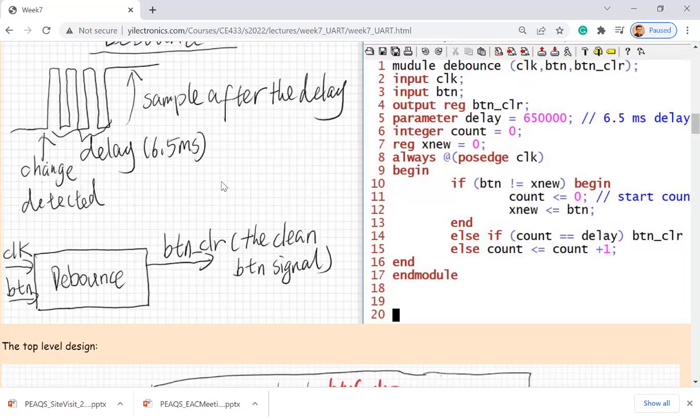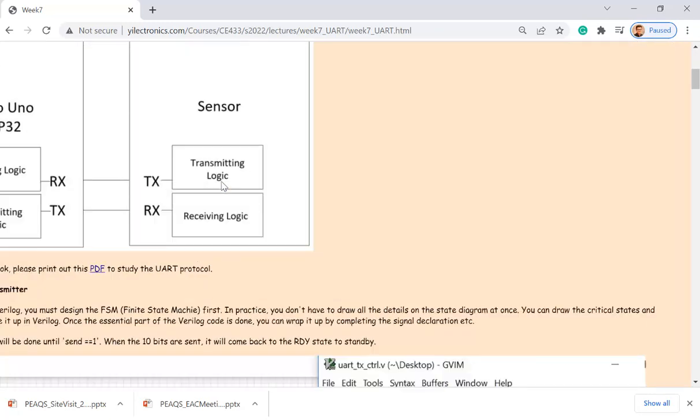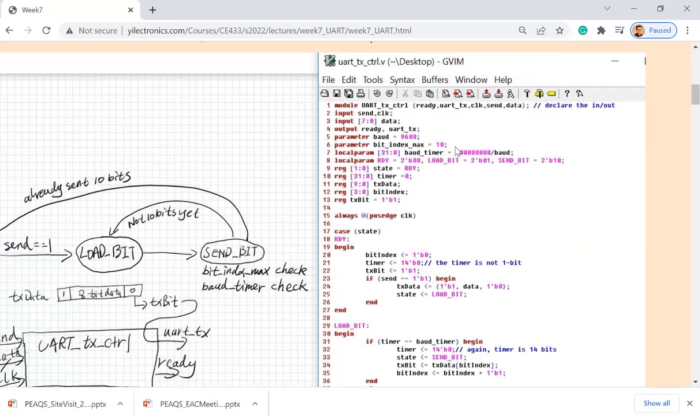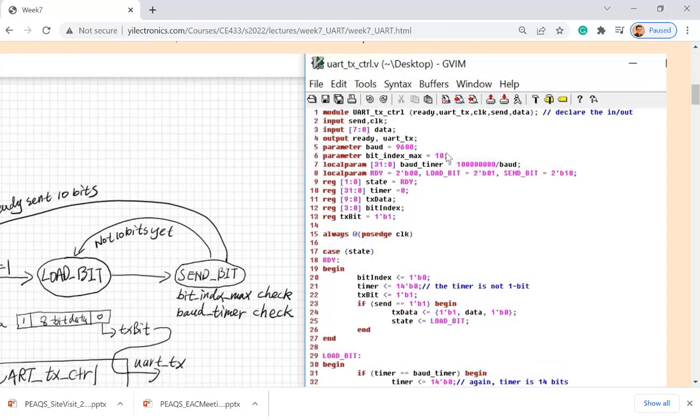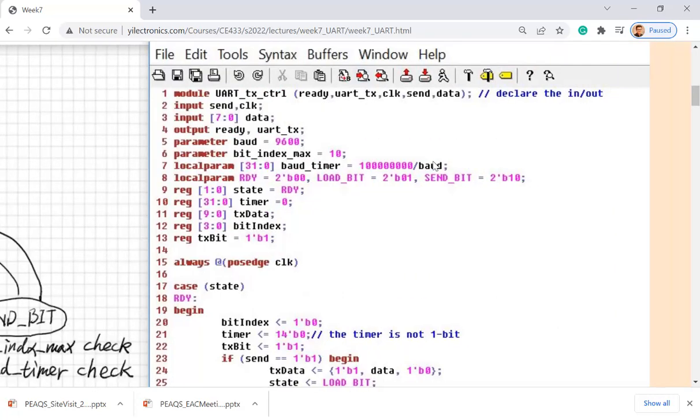Okay, and let's see how this works really quick. So that's a transmitter. That's a transmitter you want to use for the push button example. First, UART you have used in microcontrollers. The baud rate is 9600. Usually, you don't have to use 9600 definitely, because as long as the sender and receiver have the same baud rate, they will communicate properly.